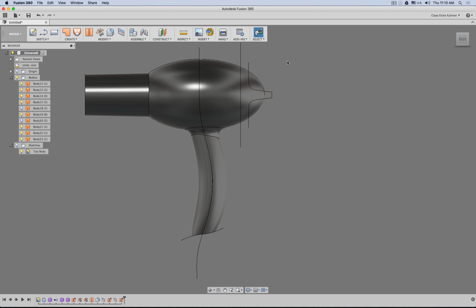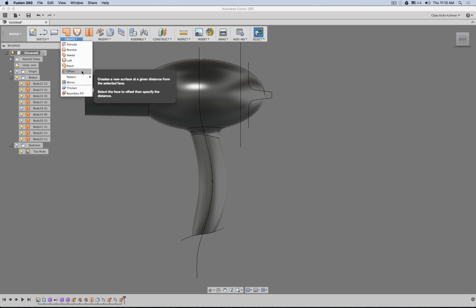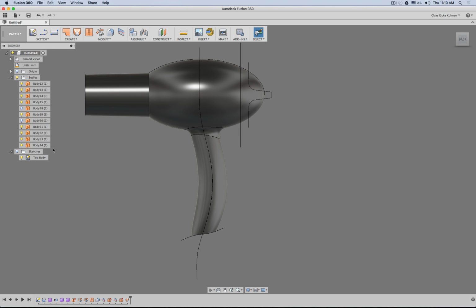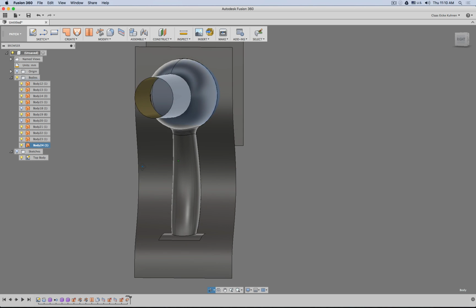Because before I continue, you remember here this will be offset. So it makes sense at this point, when this surface is nice and raw and also not stitched to all these other parts, to now create the surface offset. Again, big problem. Try to see how you can simplify problems. So in this case, it makes more sense to build this one now.